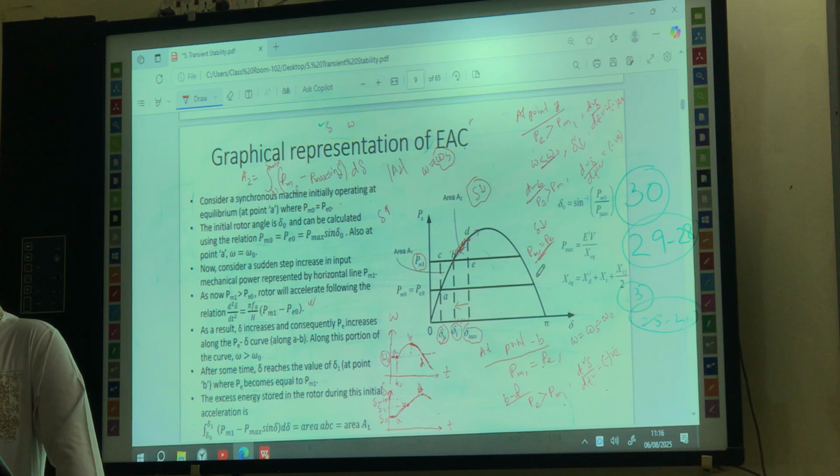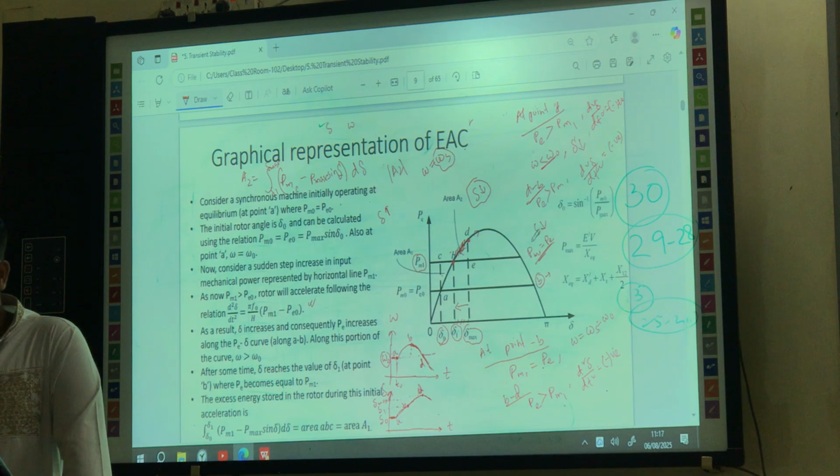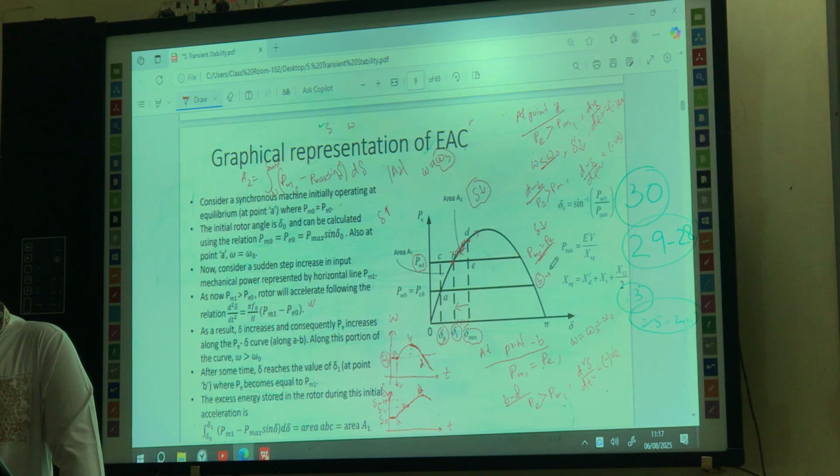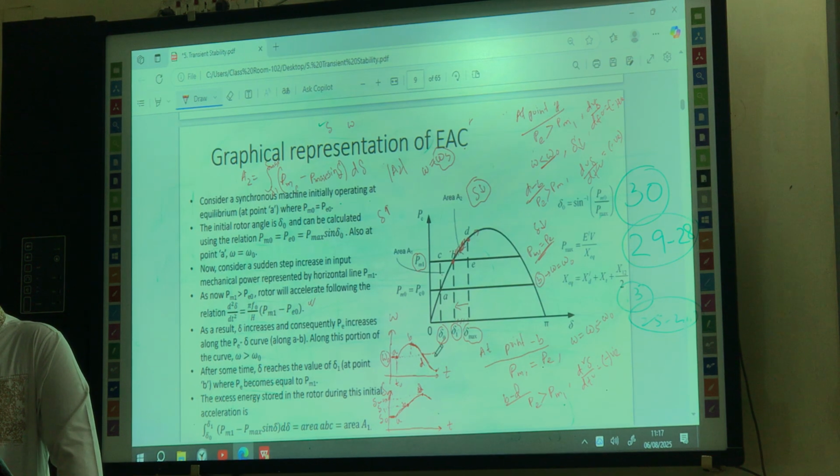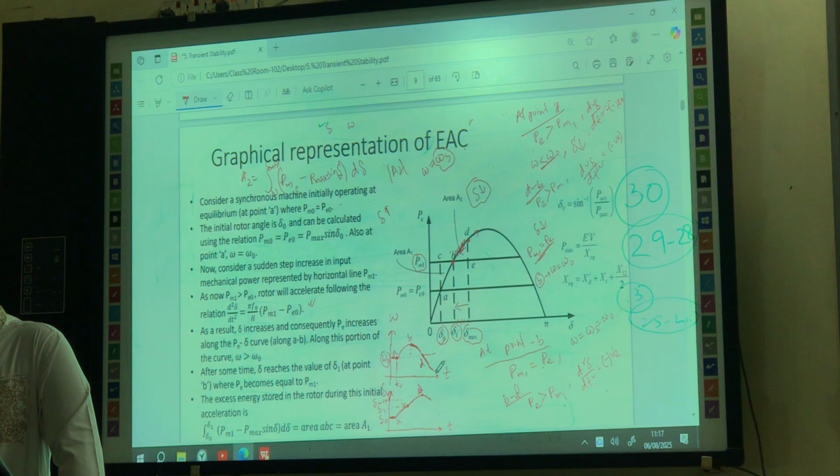So now again we are at point B. At point B, these two are again the same. That means the omega value should be equal to omega naught. But we are already at some lower value than this omega naught, right? So again it can't suddenly jump from here to here. Rather, it will actually take this point, this below point, which is point B.